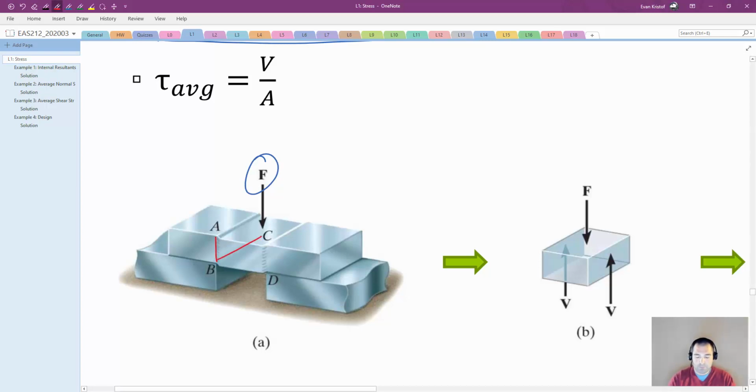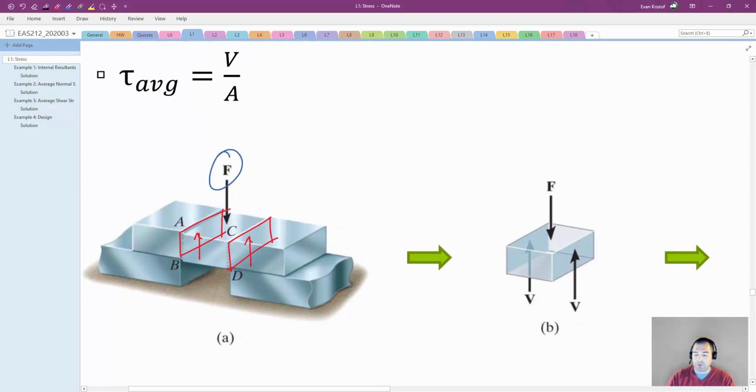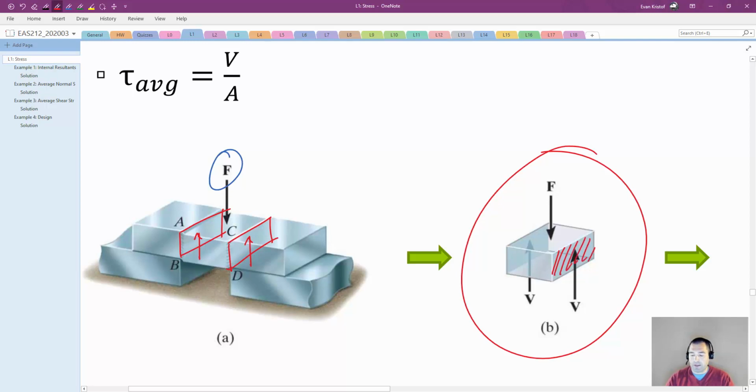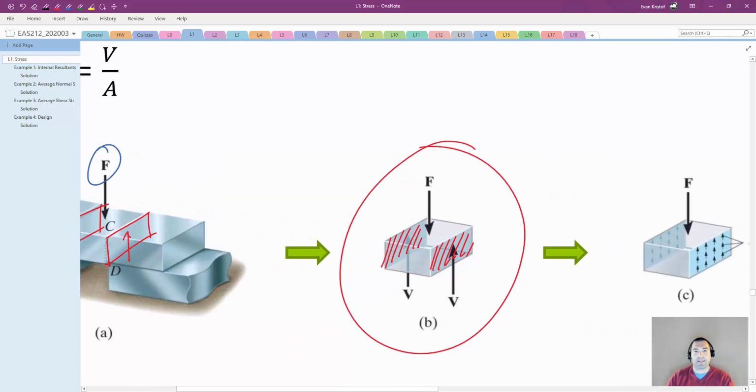on these sections here? So you can imagine, and actually, the next diagram right here basically shows what the forces will be on each of these faces. So we can do basic statics. Again, I would make a free body diagram, show a coordinate system, and use equilibrium.